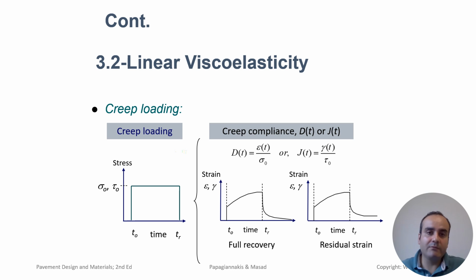In asphalt pavements, creep behavior is a critical factor in predicting long-term performance, especially in areas prone to heavy loading or high temperatures. Asphalt mixes with high creep compliance can lead to permanent deformations such as rutting, which can form in the wheel paths of the road. They can also lead to fatigue cracking if the asphalt binders become too brittle after repeated cycles of creep deformation.